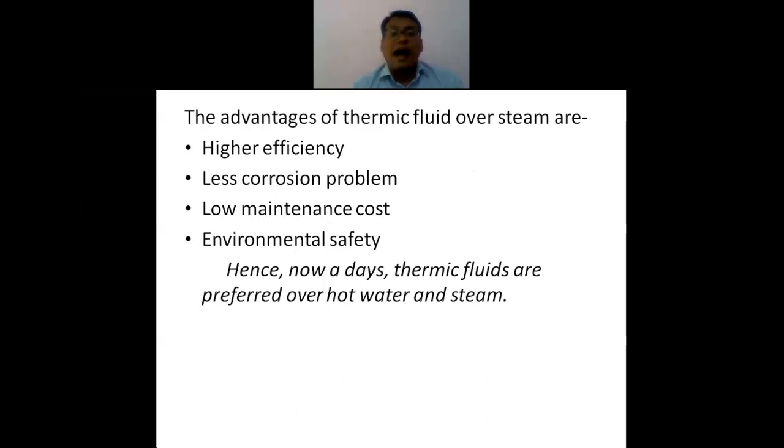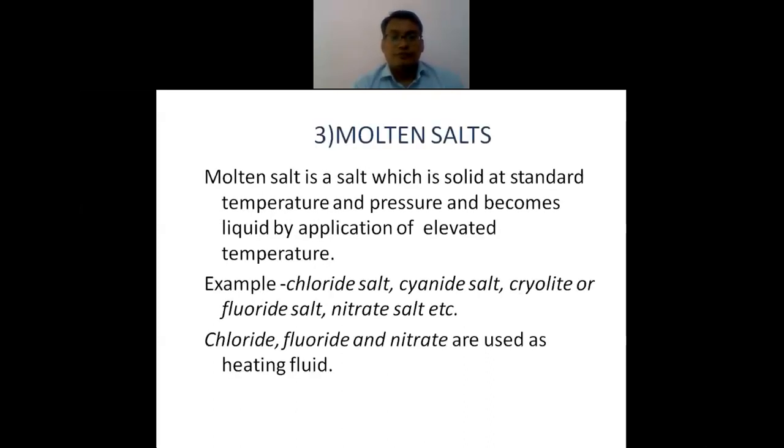Then the advantages of thermic fluid over steam: it can be used at a higher temperature, higher efficiency, low corrosion problems, low maintenance cost, and environmental safety. Then the molten salts. The salts, at a higher temperature, attain a liquid state, and these liquid salts are used as the heating media. They are generally used at higher temperatures, 400 to 600 degrees Celsius.